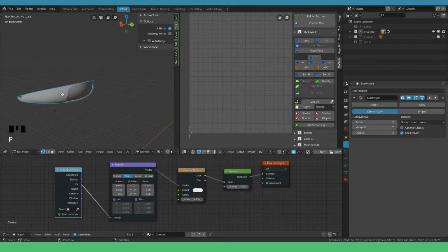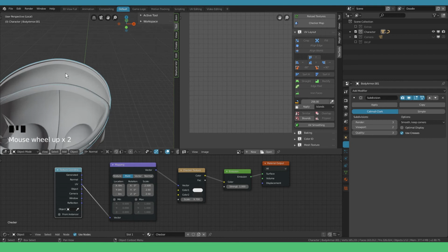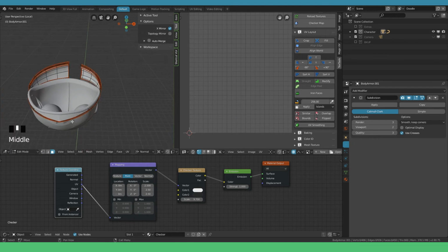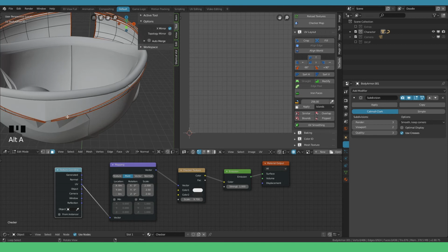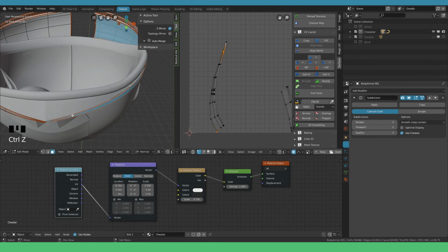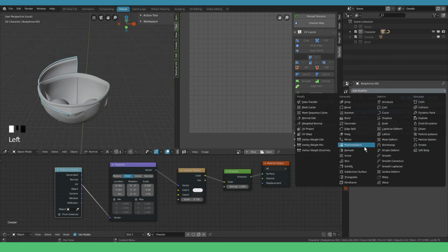First I'm gonna separate this mesh by selection. Go out of edit mode. Then select the part we just separated. Go back into edit mode. Now we want to get rid of the side we didn't do the unwrap on. Usually I'll do a loop selection right next to the middle poly loop. Delete those loops. Island select the remaining parts, best to do this in vertex mode, otherwise you have to keep selecting the poly groups. Delete those as well. Go out of edit mode, add a mirror modifier like so.